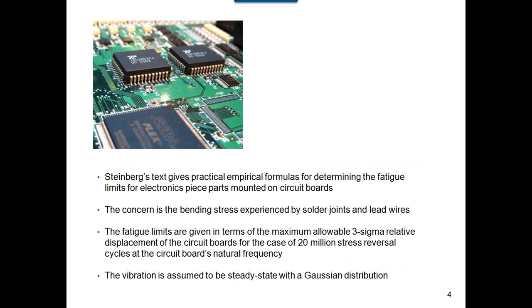So here's a circuit board, and our concern, and this comes from Steinberg's work, is that those lead wires and solder joints are going to fail, that those are the weak links. And the circuit boards themselves are going to be undergoing bending vibration. Now if you want to get into all the theory, there's also torsional vibration modes and membrane modes and longitudinal modes and all sorts of other vibration modes. And we can even start talking about wave behavior. But the driver is going to be the bending modes, and more particularly the fundamental bending mode of the circuit board. That is what's going to induce most of the stress into those lead wires and also the solder joints.